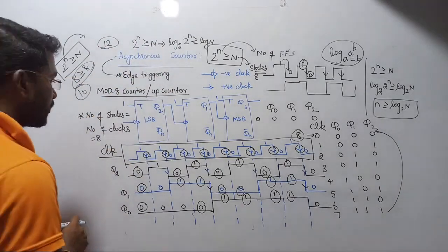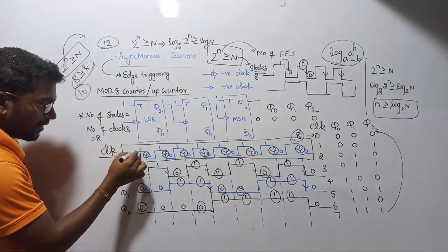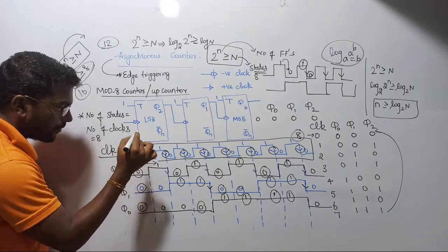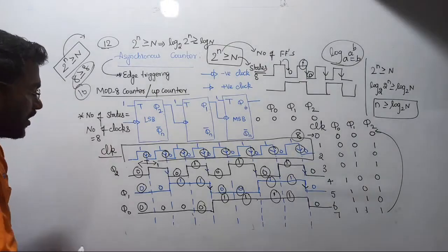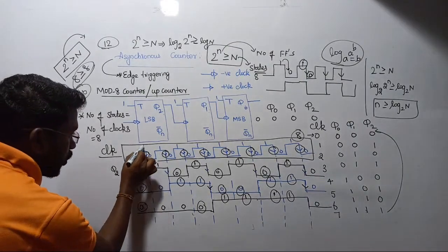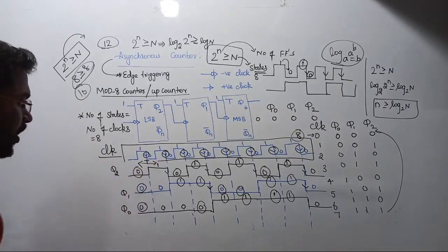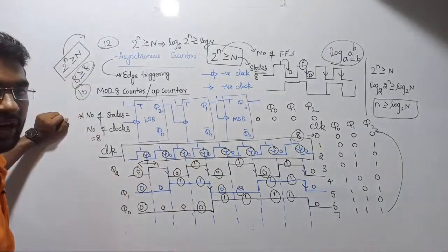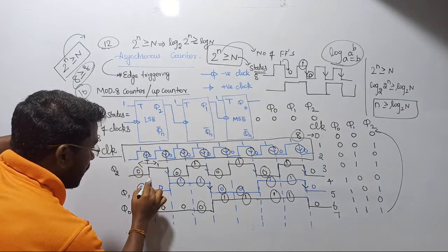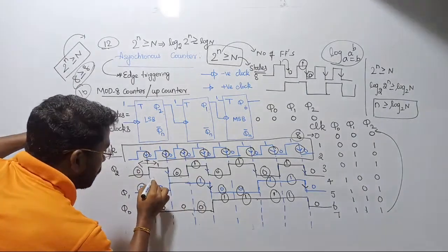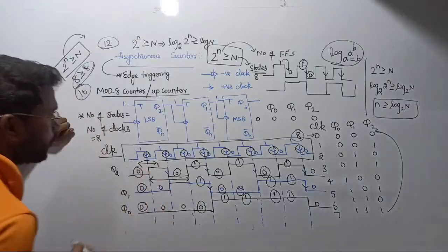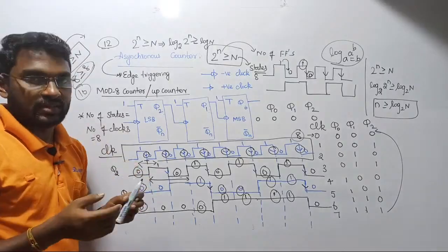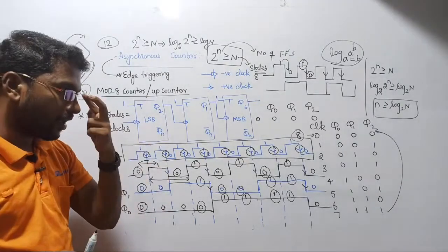And then let us write the frequency, right? So frequency, in the sense, guys listen, on the input side this is our clock. Let us define the time period of one clock, let me simply call it T. This is the original clock time period. Now if you observe, the output of the first flip-flop acts as the clock for the second flip-flop, correct? So if I consider this as the clock, what is the frequency of the output of the first flip-flop? What do you mean by frequency actually? Let me talk in terms of time period itself.